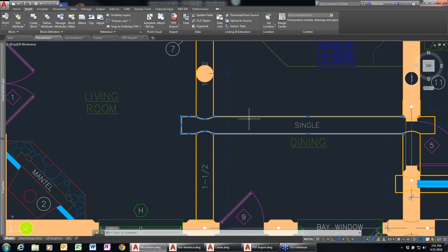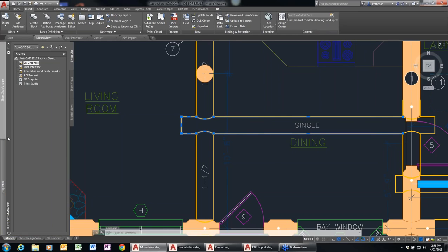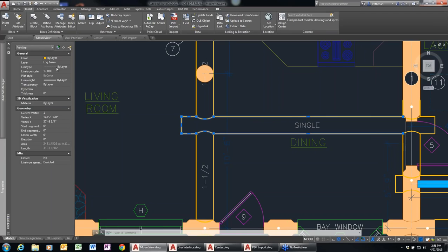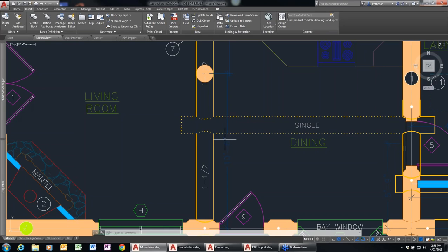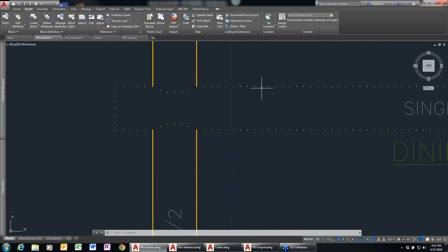But I'm going to pick on this polyline, and I'm going to change this from line type by layer to dots. And the first thing you're going to see is actually the dots have a thickness to them. It's not just a single pixel. So you can actually see something with dots. But the cool thing here is you can see if I move my cursor over the gap, I don't get any kind of a selection. If I pick on the dot, right, it highlights the line. And that's how AutoCAD has always worked.